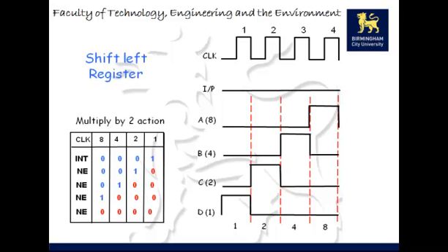This application should not seem that alien to you because you've seen it in embedded systems where the ADC results are in 2 8-bit registers and they're combined to make a 12-bit analog to digital conversion result. Because it's an 8-bit processor, the values go into 2 8-bit registers, and then you combine those registers. But in order to get the right binary weightings, you're shifting left, as I remember. So it shouldn't seem that alien to you.